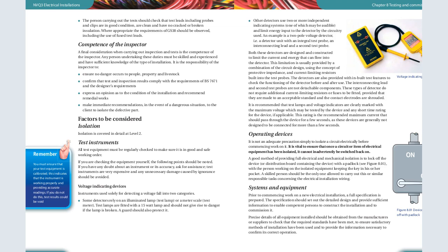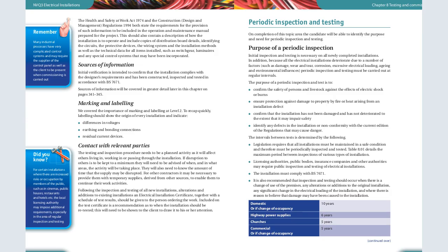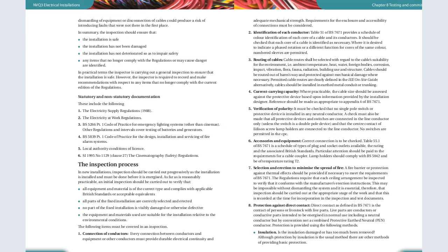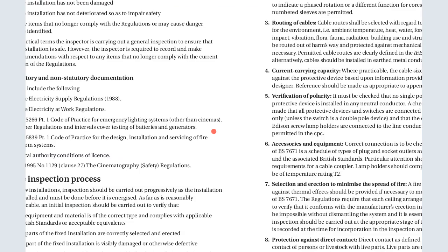For code number 3, first, that code means that improvement of the installation should be done, and the examples of this code are absence of circuit protective conductors, sheath is not in an enclosure, and absence of identification details.